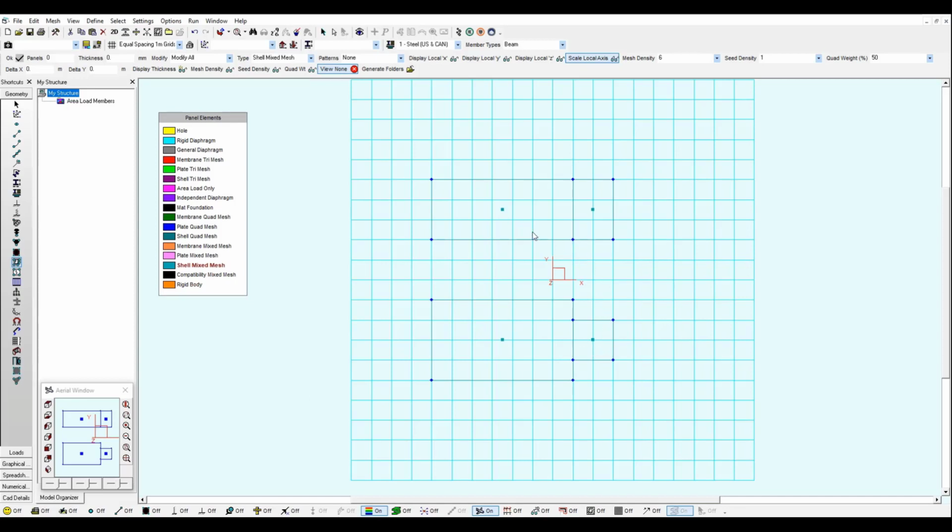Some of you may think that the size has something to do with these panels, and that's the reason why the dimensions stay the same. The truth is that it depends on the thickness and the size. Let me give you an example. If I go back and I undo, I can still have my original configuration of overlapping panels. And now I'm just going to change the thickness to 1.